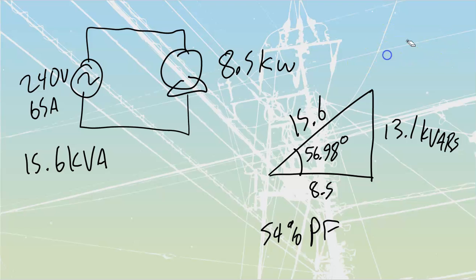Lovely. We'll get rid of that there. Now that we've got the kVARs, we know what size of capacitor, right? Because we've got this circuit inside of here. That's a motor. It's inductive. We knew it was inductive because they said that they wanted to know what the capacitor would be. So we know the size of the cap that we're going to place onto there.